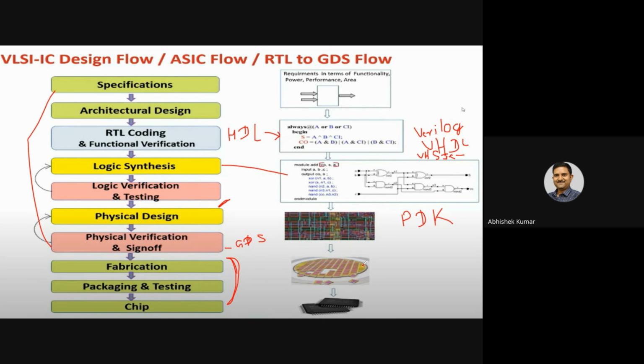Okay, so first of all, they will take a silicon wafer. On the silicon wafer, we have to do more than 30 or 36 steps. We have many repetitive steps like oxidation, lithography, etching. Lots of physical and chemical steps are there. After that, the information given by this GDS file, they will map onto the IC, and finally they will cut the IC into packaging form, and we will get one chip in the market.